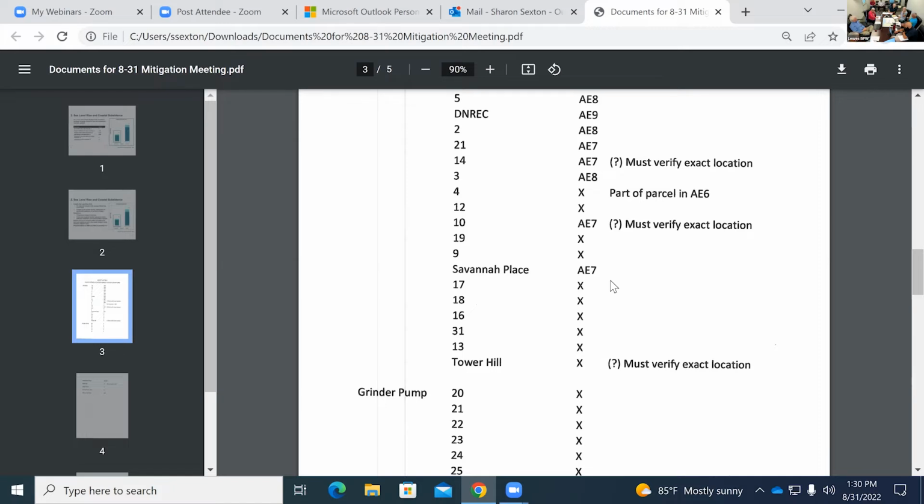Well, would it be as simple as transferring a datum across the town? So if we're working to elevation 11.6, let's say, as 7, we could look at any other thing that's outside the floodplain and see whether it's less than 11.6. We could shoot all those elevations if we don't have them.